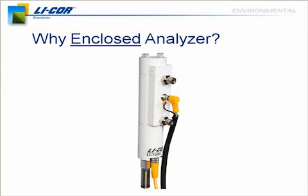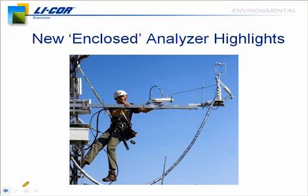Just a couple of highlights for this enclosed analyzer approach are that the entire system, including the gas analyzer, airflow through the analyzer, and ability to log data, can operate with about 27 watts of power nominally. That's new and exciting for this market because in the past, to get a really low power gas analyzer, you had to go with an open path.